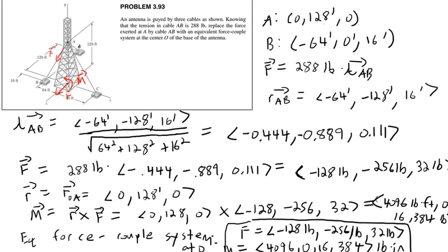And this entire thing is our solution. In other words, if I wanted to move this force down here, an equivalent system would be this force vector and this moment vector. Just the subscripts on both the force and the moment would be O, right? Subscripts are somewhat arbitrary, but I could call this moment at O, force O and MO, but I'm not really that picky on subscripts.